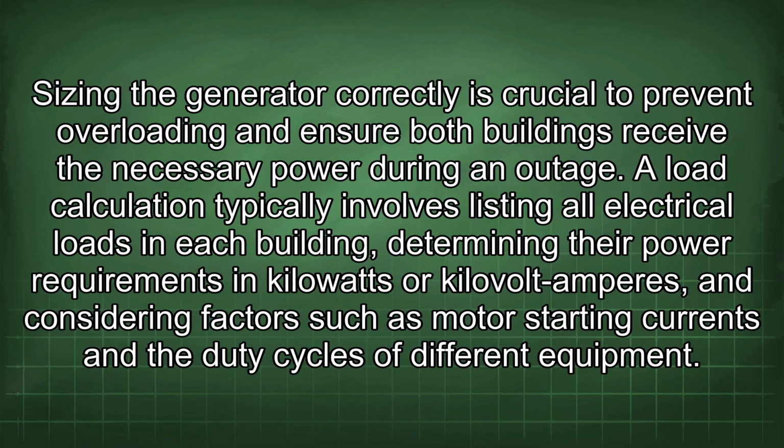A load calculation typically involves listing all electrical loads in each building, determining their power requirements in kilowatts or kilovolt-amperes, and considering factors such as motor starting currents and the duty cycles of different equipment.